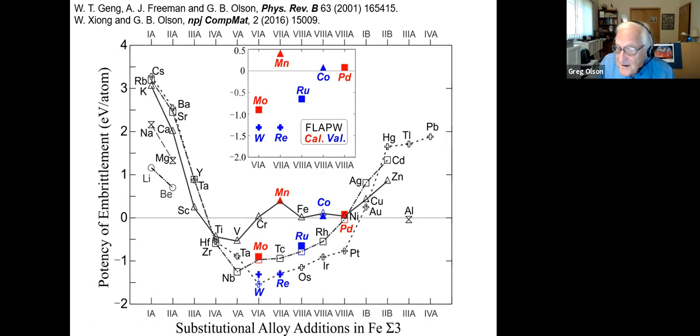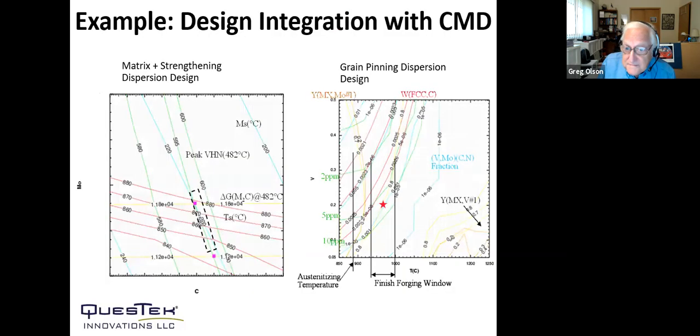So that's one example of a surface thermodynamic genome that's coming entirely from the DFT calculations. The actual parametric design is performed graphically as represented here. This is in the example of the stainless landing gear steel, where we're looking here at a pair of composition variables, starting with optimizing the nanoscale structure that is produced in the final stage of processing. This is looking at the combination of the thermodynamic driving force plus phase fraction to predict the composition range that meets our strength requirements.